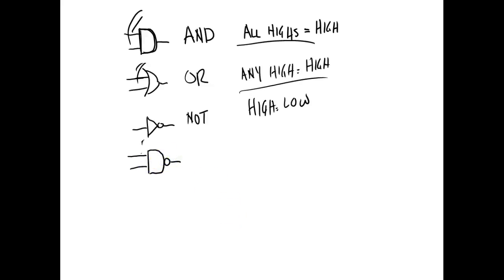So we call this a what? If it's got a low active input. That's not true. Let's go ahead and get this. What we do to get the NANDs and the NORs is we look at what we call the active state of the input, and we compare it to the active state of the output. Here the inputs are high active, the output is low active, and that's what we say, so it's low when it's true.